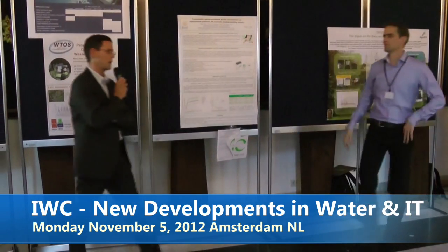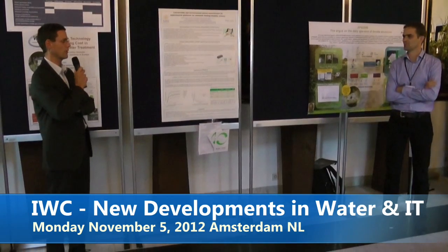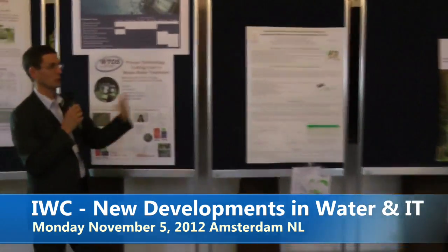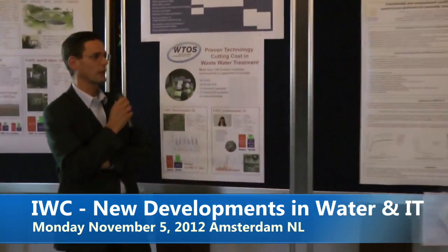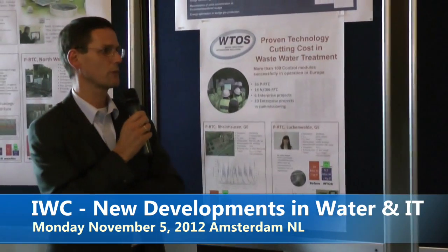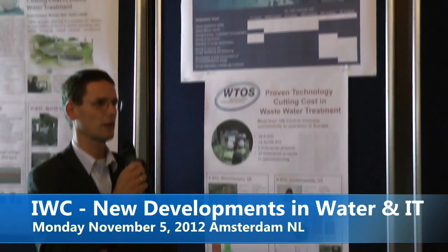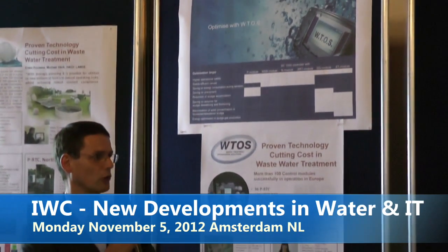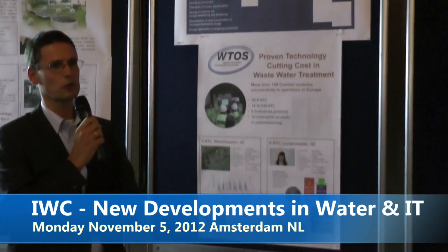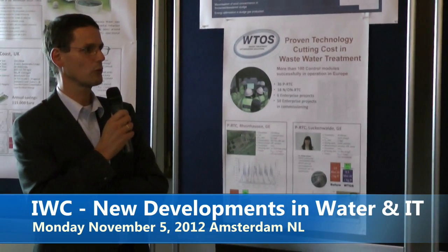So we have 2 different types of controllers. One user interface might be our standard SC1000 controller, as you see here. All the control parameters, for example for phosphorus removal, what kind of chemical is used, what's the active substance, what the controller parameters are, those are added here in that SC1000 display module, and that's the way we communicate to our controller. Or we also have some bigger applications where we have a small industrial PC where we are also able to combine several modules in order to have a plant-wide control.